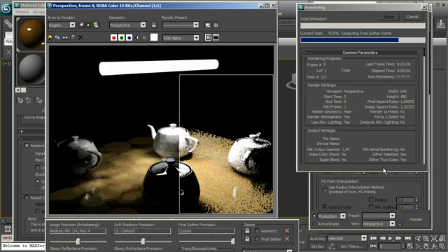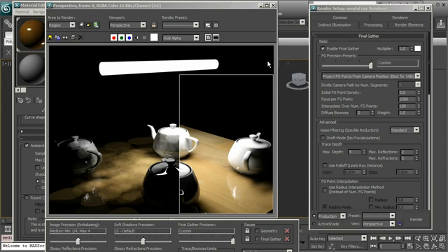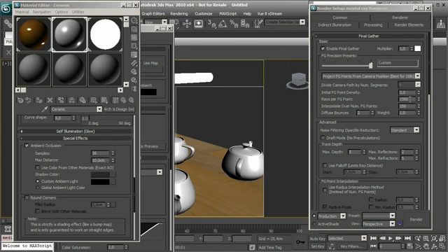You have also to imagine that we can use different colors for the lighting and different, for example, also maps to decide the area that will emit light or not, and then we see a fast test. So you see that the final gather is faster than before, and we hope to have a really smooth result in the final rendering. Okay, I think that it can be okay, and we have also the final gather, so it can be a really good compromise.